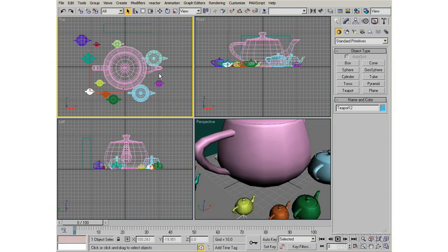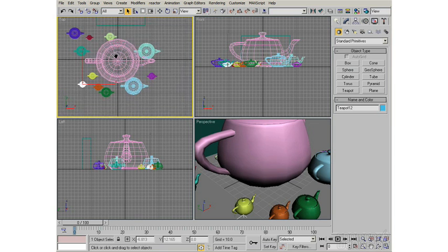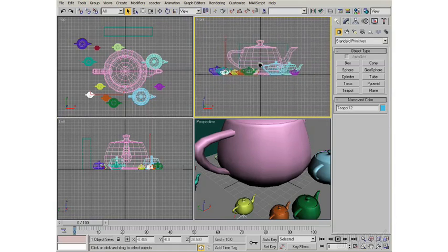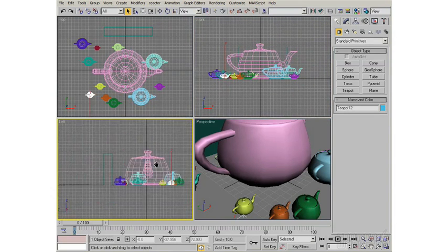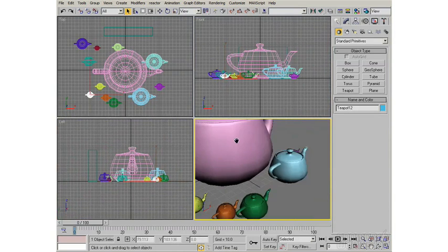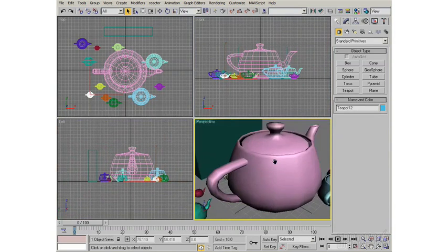The central one to 3D Studio is the middle mouse button. You probably do have a middle mouse button, even if you don't think you do, because if you have a mouse with a rolly wheel on it, if you push on it and hold it down, that acts as a middle click. When you middle click in one of the views, it acts as a pan. You see it turns to a little hand and allows you to pan the view around. Works in perspective as well.